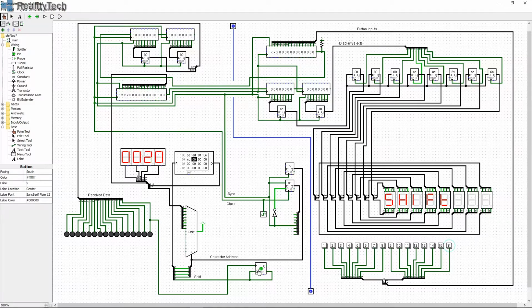We have a D-type latch here. So the way the D-types work is when you wire the D-type like this, sorry, D-type flip-flop, D-type latch, whatever you want to call it, every time you hit this clock, then the state of this will change. So if this is 0 and you hit this with a 1, which we'll do now, that will go high and it will stay high. If we hit it again, it will go low and it will stay low. And then this generates the 5th bit for our EEPROM. And that's how it all works.